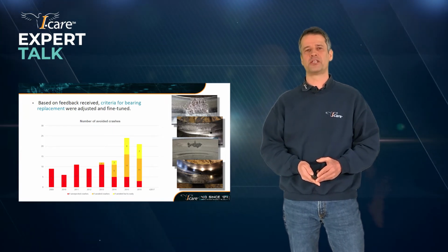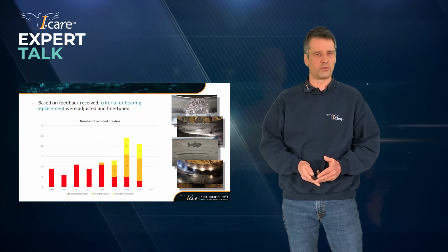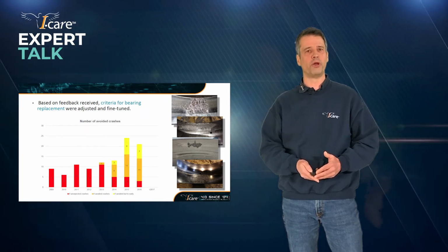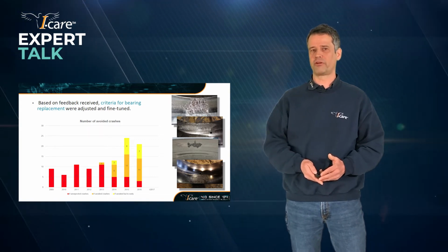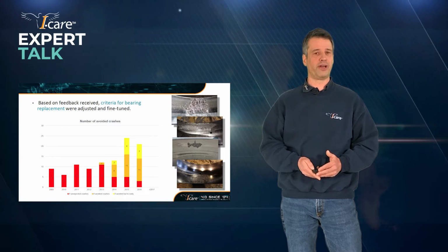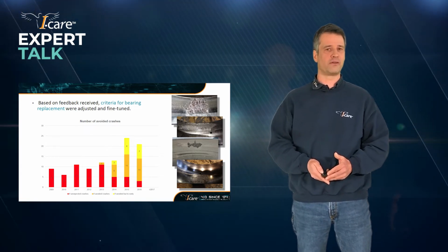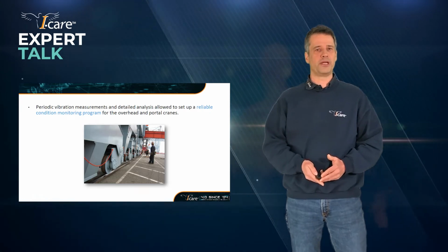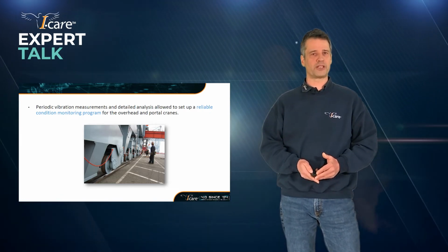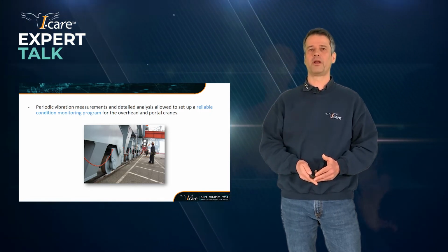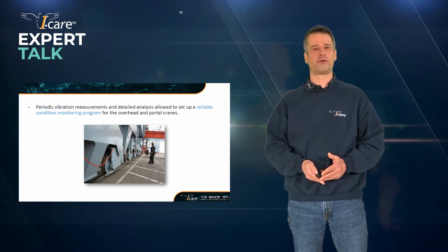in a very early stage, where you could say, okay, there is something that we see on the bearing, but we consider that this is too early to perform a replacement, and we should have continued to monitor that type of bearing. So based on this, it was possible to fine-tune our analysis and to get even better results in the years after. So we can conclude that based on that experience, we were actually able to provide a monitoring program which works quite reliably for these overhead cranes.